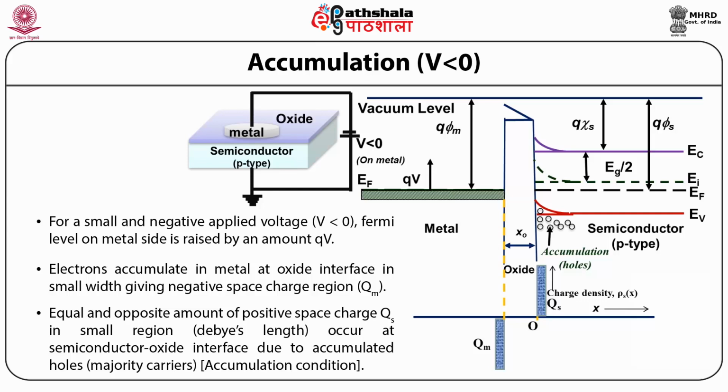Therefore, there is an enhanced concentration of holes near the semiconductor surface with a consequent upward bending of energy levels. This is known as the surface accumulation condition.